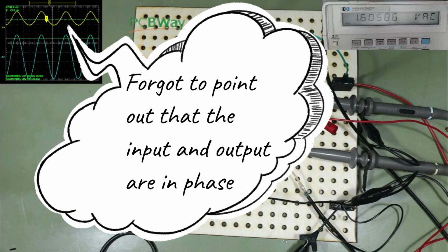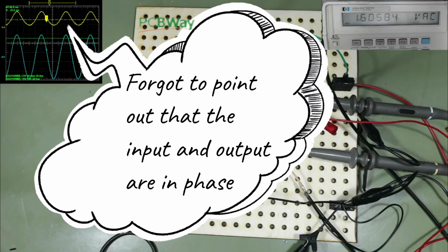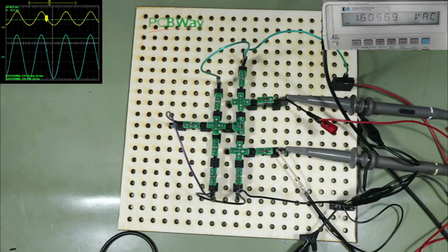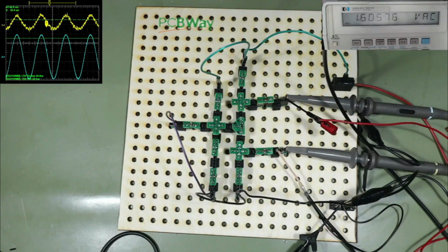And the trace on the screen from the oscilloscope is using the Handtech PC control of the scope, so it's not just a printer. I can move things around just to show you that it's not just a static photograph. It's got a lot of averaging on to reduce the noise, as my bench is a bit noisy. So there you have it, the AC characteristics, or gain anyway, of this circuit. And now we'll go back and see if we can calculate it to see how close it is to the